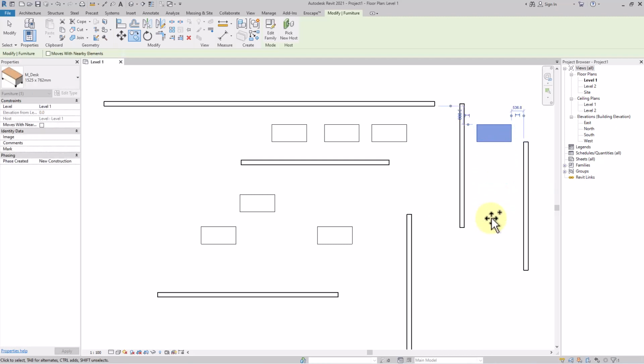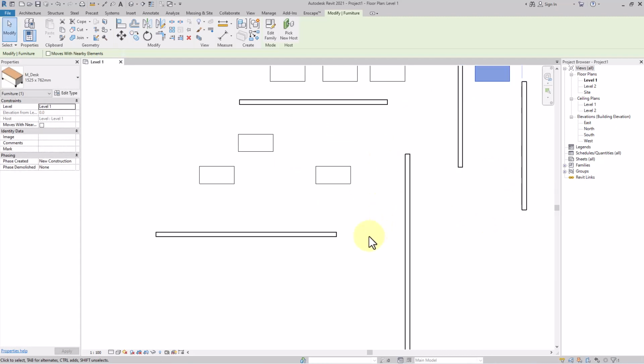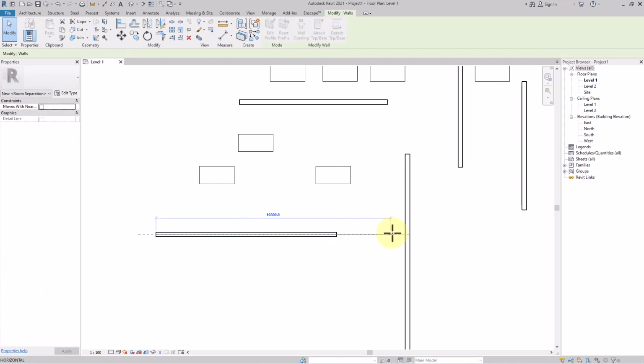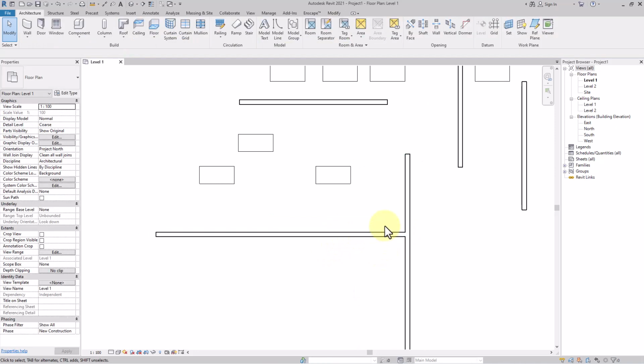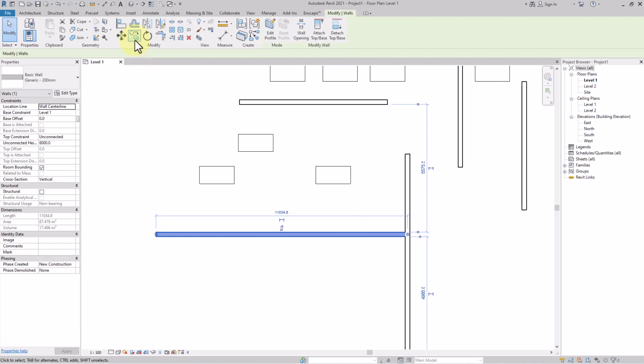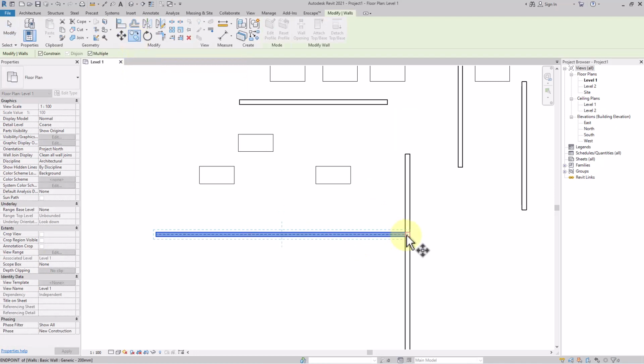Alright, Escape. Disjoin again, here you have Disjoin. For example, if the wall is joined with this wall, now you want to disjoin and you want to copy this one. So select this one, you can click the Copy command again. Now you can just define any point, because it's Ortho, that's why it's not moving anywhere else.